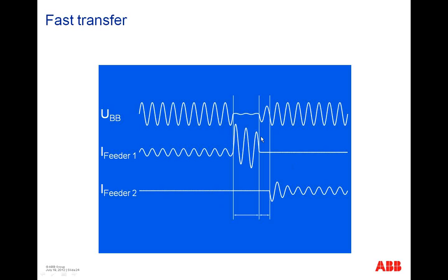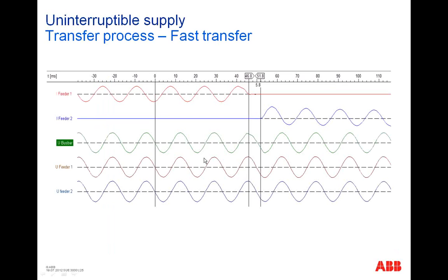And what is happening when the busbar is isolated? I explained before in the slide. The running machines work like a generator, and you see here the feedback energy from these machines to stabilize the busbar voltage during this transfer, during this small time gap, and stabilize the busbar voltage in this moment. This is made a better example.